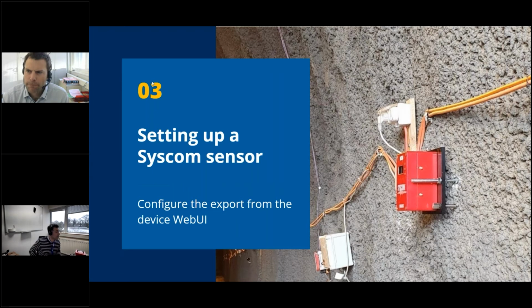I think we have another question about whether you have the availability to measure vertical displacement with an accelerometer during an event. So not directly. These devices, the MR3000, can have a velocity sensor or also an acceleration sensor in some configurations. Usually it's velocity, I would say. And then, as post-processing, you can obviously integrate the signal to get displacements and then analyze the displacements. But it's not a direct measurement of displacement. It would be first velocities, and processing the signal would allow you to get access to displacement.